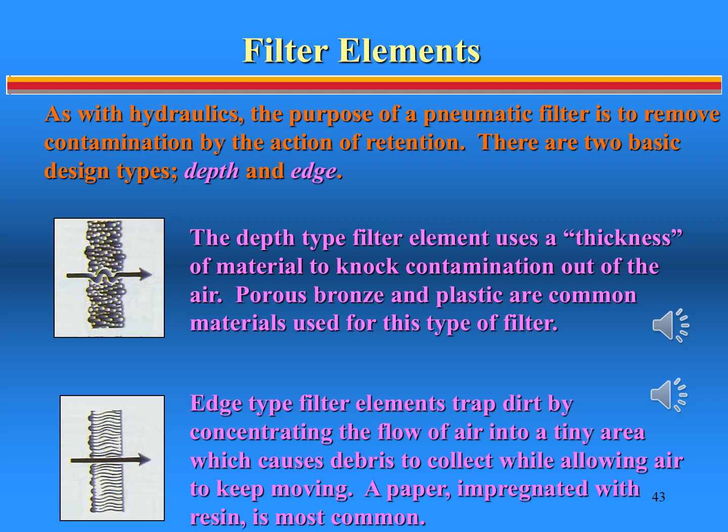Water separators remove condensate either with a centrifugal design or a coalescing principle. A centrifugal separator causes a rotary motion in the air, forcing particles to accelerate in a radial outward movement. Once they reach the outside, they drain into the bowl. These are effective for removing water droplets as well as dust and dirt particles larger than 5 microns in size. No maintenance is required for this process.